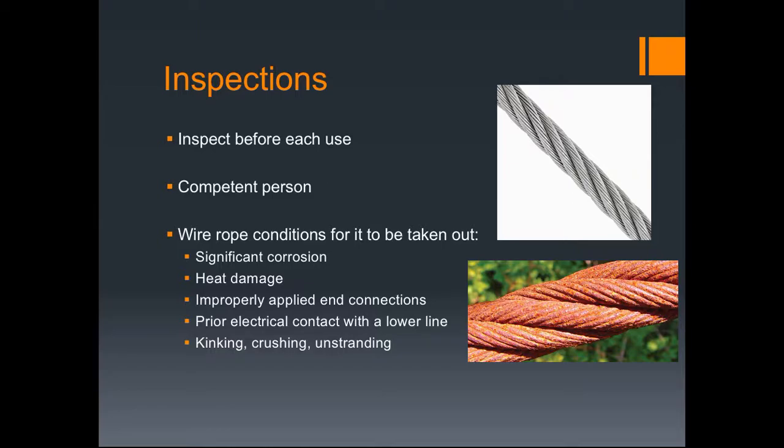Now for inspections, it is a requirement from OSHA that you inspect a crane before each use and after using a crane, and this inspection should be done by a competent person, and OSHA defines a competent person as one who is capable of identifying existing and predictable hazards in the surrounding or working conditions which are unsanitary, hazardous, or dangerous to employees.